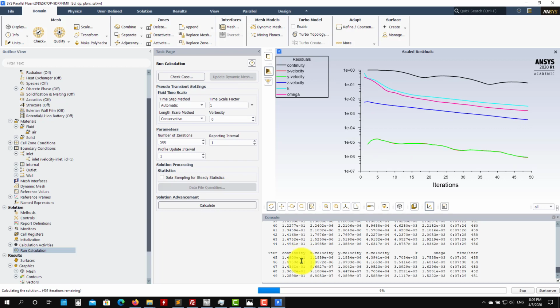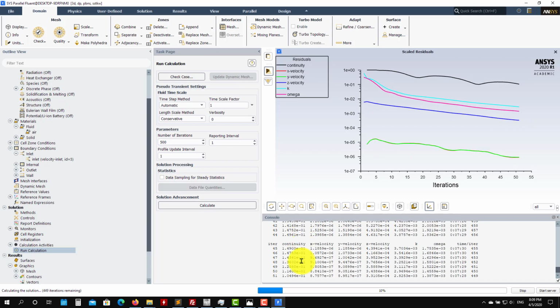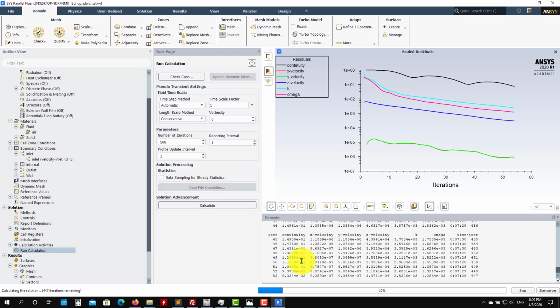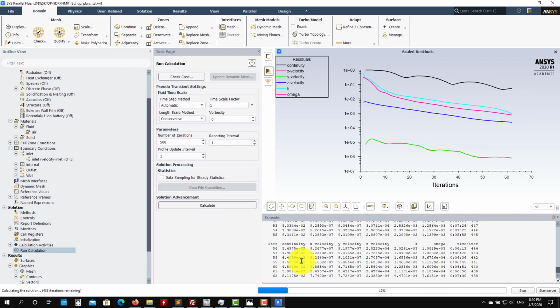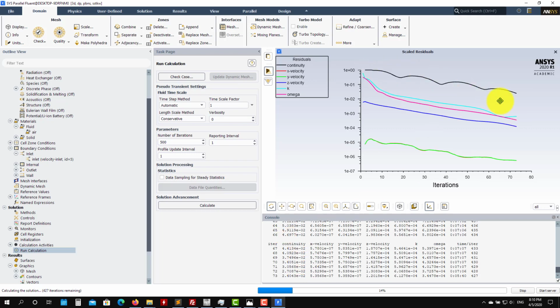But there are some cases where you have very strong physics, coupled physics, or you are using very fine meshes, where probably the coupled solver is the best option and will converge faster. Again, be careful with the memory use. Okay, so now I see also that the convergence rate is very different. The other was smooth, here it is bouncing a little bit.